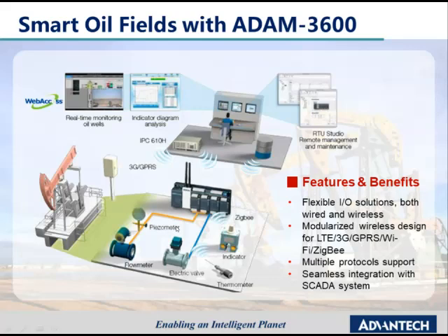Advantech 3600 has a flexible I/O solution, both wired and wireless. The modularized wireless design for the LTE, 3G, GPRS, Wi-Fi, and Zigbee gives Advantech 3600 the ability to support multiple ways of communication and allows the data to be seamlessly integrated with the SCADA system.